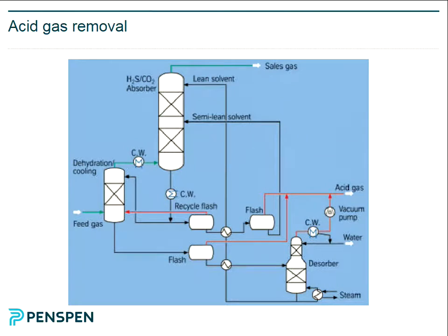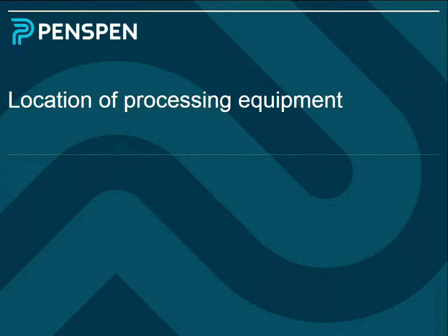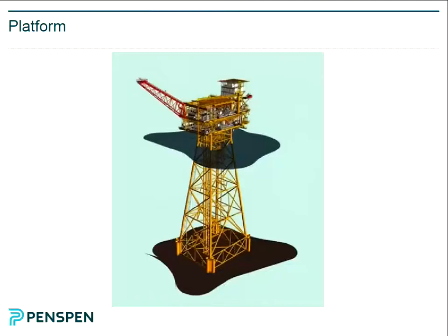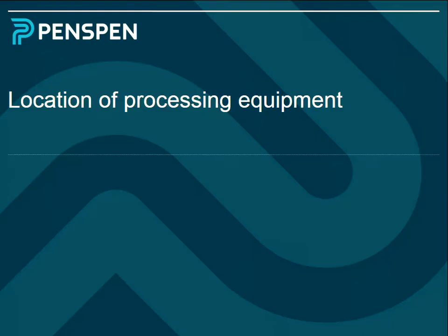So jackets are typically, but there are some deep water jackets, but typically associated with relatively shallow water. 160 meters is, I would say, jacket territory. There have been 300 meter jackets before, but they're some of the largest in the world. But the more common technology now is to put it on something that floats, like an FPSO, floating production, storage and offloading, with a tanker.